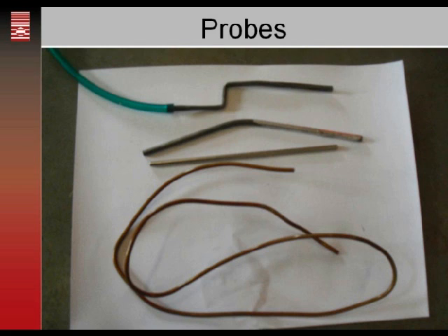You can close doors on these kinds of tubes. It's a good idea to also add an extra tube that you can throw up into the attic farther. So if you're doing the advanced zone pressure diagnostics where you're removing the attic hatch, you want that hose up farther into the attic, where it's not in an area of air movement, so you have a more stable pressure.